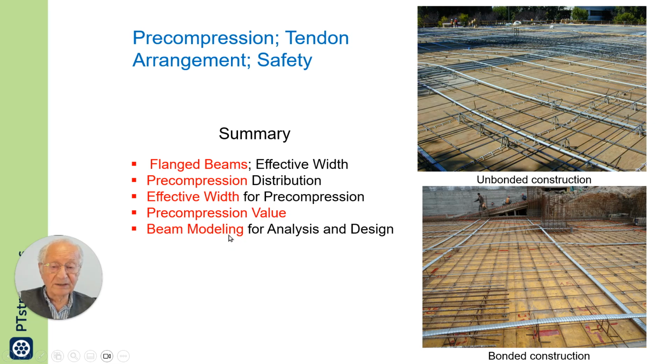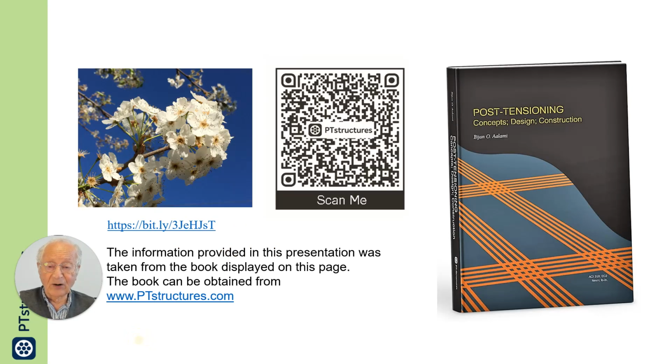I talked about beam modeling, how it can be modeled either attached to the flange or not. Most computer software available for purchase on the screen show the stem attached to the flange, but in the background they model it detached. And then I talked about judicious application of tendons, emphasizing to put tendons where it is beneficial, not where it is harmful.